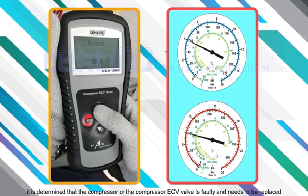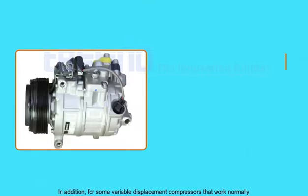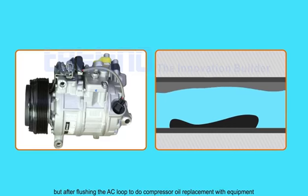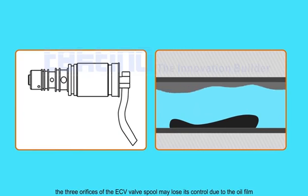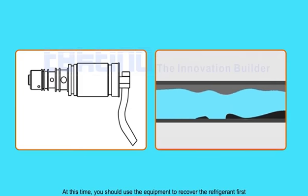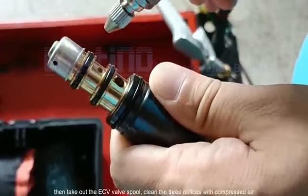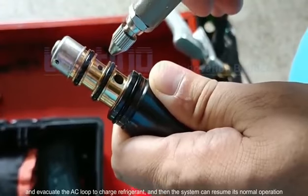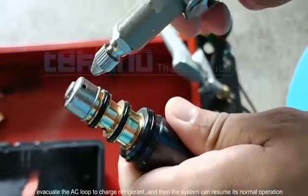In addition, for some variable displacement compressors that work normally, but after flushing the AC loop to do compressor oil replacement with equipment, the 3 orifices of the ECV valve spool may lose its control due to the oil film. At this time, you should use the equipment to recover the refrigerant first, then take out the ECV valve spool, clean the 3 orifices with compressed air, and evacuate the AC loop to charge refrigerant, and then the system can resume its normal operation.